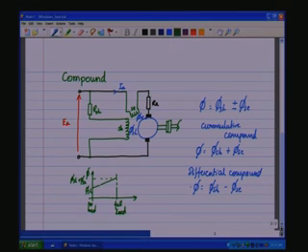the field starts from phi shunt value and starts decreasing. As the flux decreases, the speed will increase to maintain the back EMF constant. This means that in the differential compound there could arise some instability due to increasing speed, and that could cause some runaway issues. So, normally the compound motor is not wound for differential purpose. It is normally wound as a cumulative compound motor.